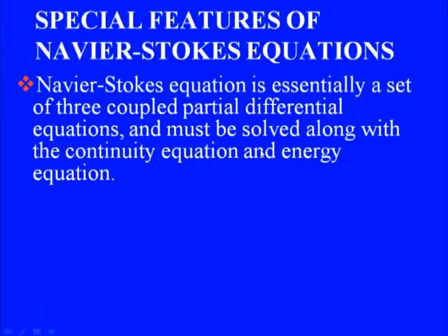So this is what differentiates the Navier-Stokes solution from the solution of a transport equation, or let us say simple heat conduction problem. In fact, in CFD literature very often when we talk about Navier-Stokes equation, what we mean is the collection of continuity, momentum and energy equations taken together, because all of these are coupled and they must be solved together to obtain our flow variables, that is to say the velocity components, density, pressure and temperature.